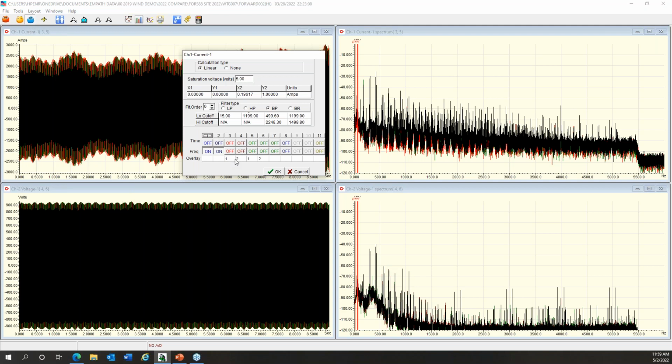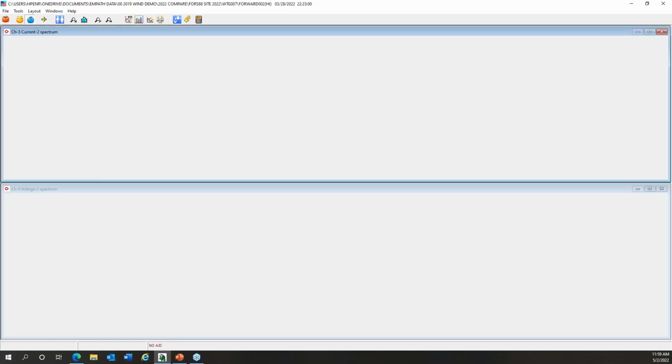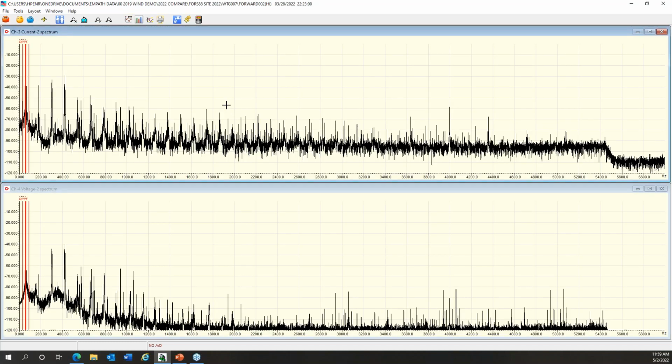And just to make life simpler, let's get rid of those signatures. So we're just looking at one phase. Much easier to see. There's the second harmonic of the firing frequency. So if I bounce back, the other one's going to be somewhere around here, and very low resonance. So I know where this is. So they actually have some relatively heavy loads nearby. So they're not going long distance.